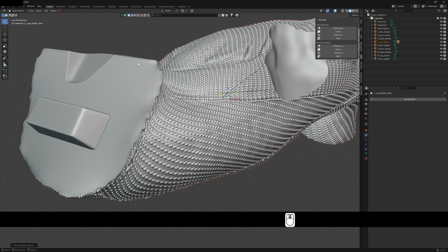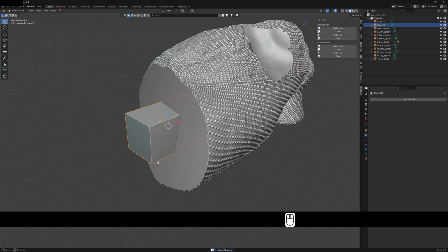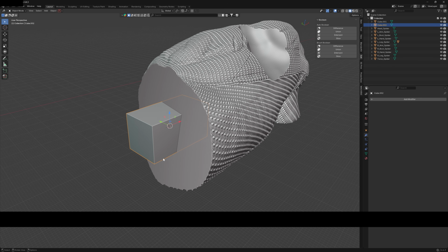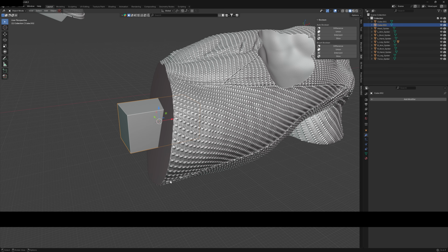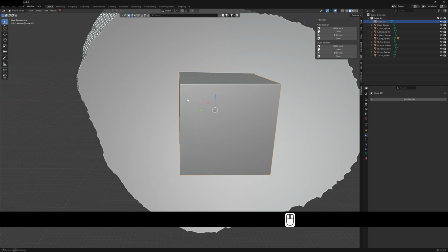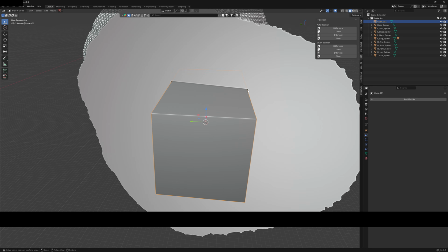I'm not going to press Alt H to bring back the object we need to cut something out of. I'm going to hide the object that's already done. Select the larger of the two cubes, which you can see because the smaller one is hidden beneath it. If you drag over, you would select both of them, but if you just click that, it'll select the one object you can actually touch, then the other leg, then Difference, and then you'll see you've got your original cube there with your tolerance.